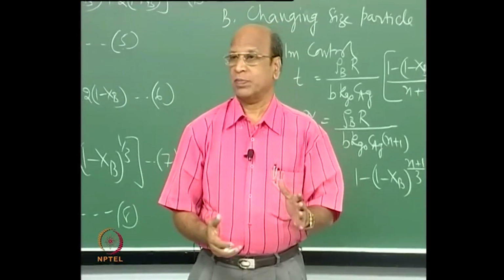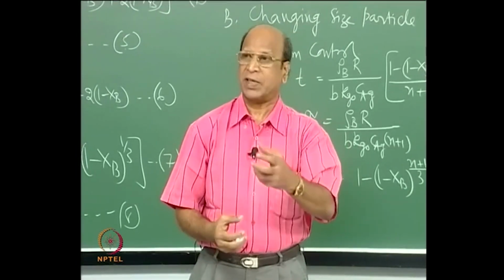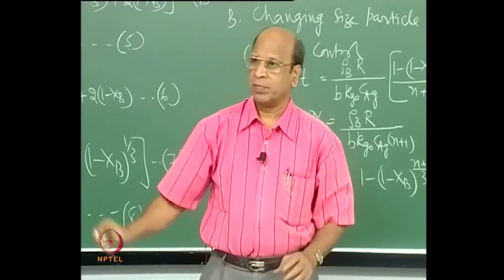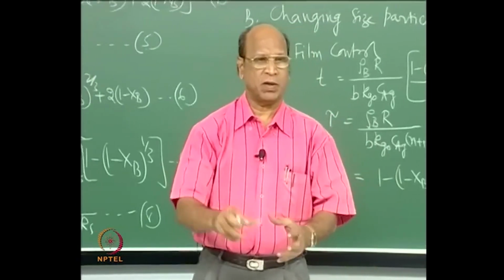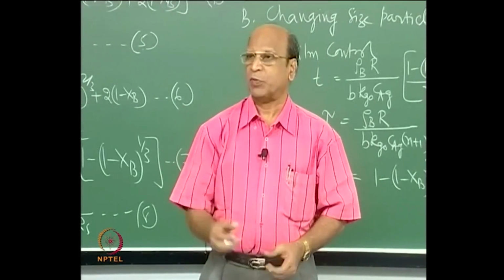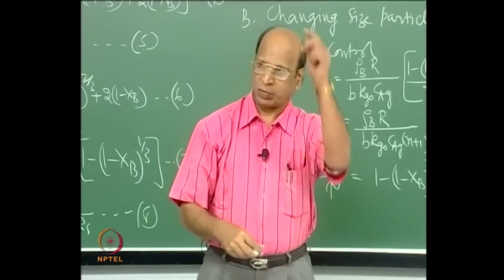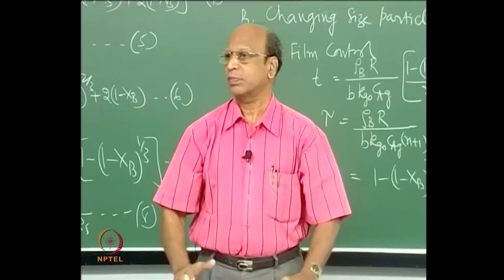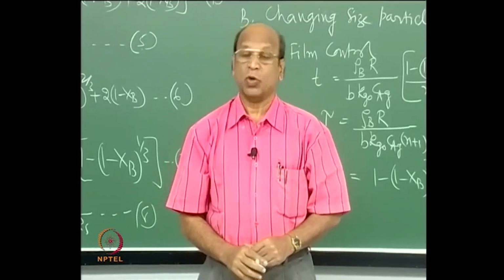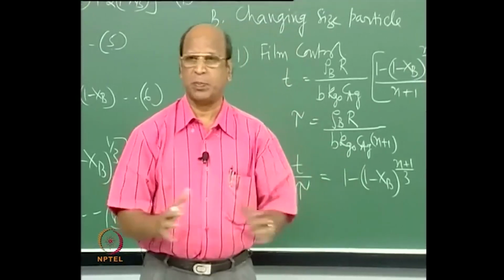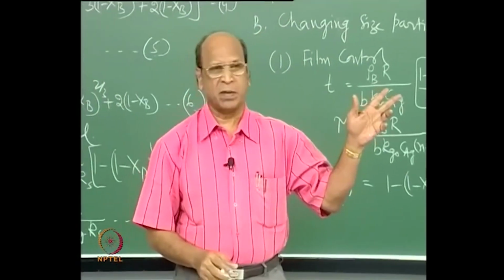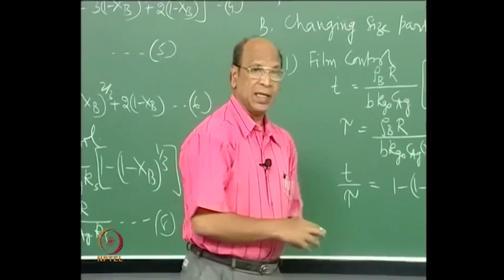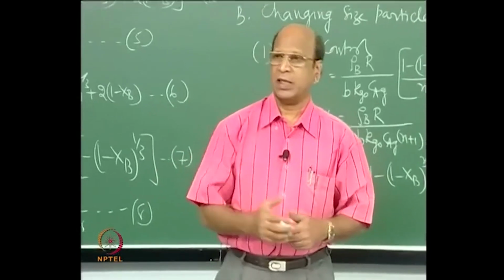Both are plug flow, okay, because in the moving bed you fill up the entire column as a packed bed and then just remove solids through some small hole with control at the wall. So, that fixes the actual flow rate from the top and bottom. Then the entire bed will be slowly moving down, that is why we call it a moving bed reactor. So, any reactor you take, we can always break into our basic contacting patterns, whether mixed flow or plug flow.